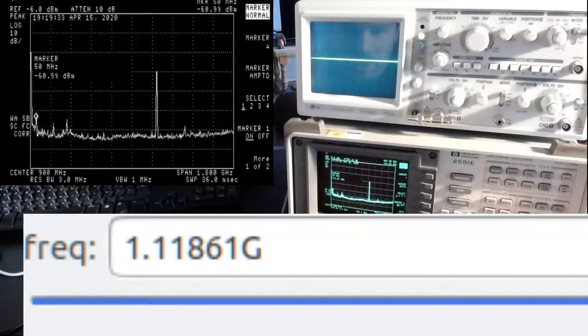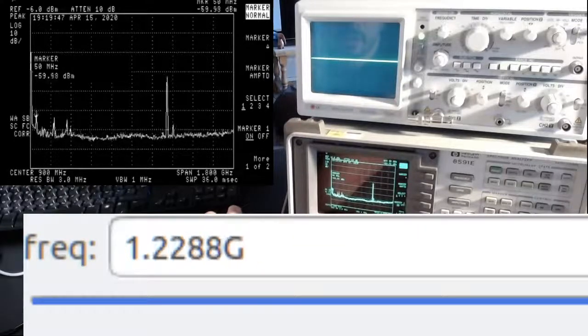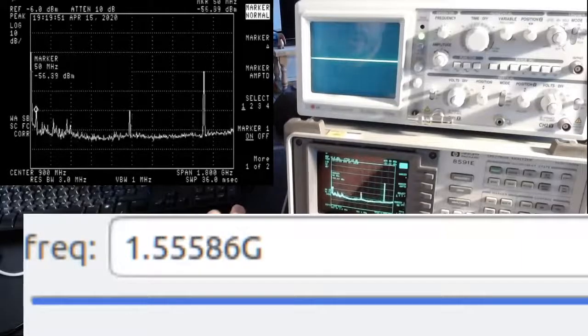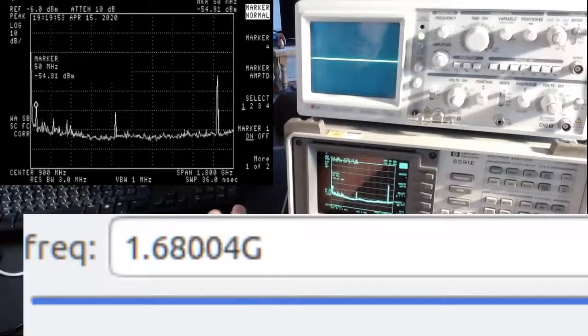So yeah, it's only 25 dB down. So it's not even true that the HackRF maintains this minus 30 dB with respect to the carrier. Yeah, no, that's not the case. This looks at 800 megahertz, so this is pretty bad. I mean, pretty bad, relatively speaking, of course.